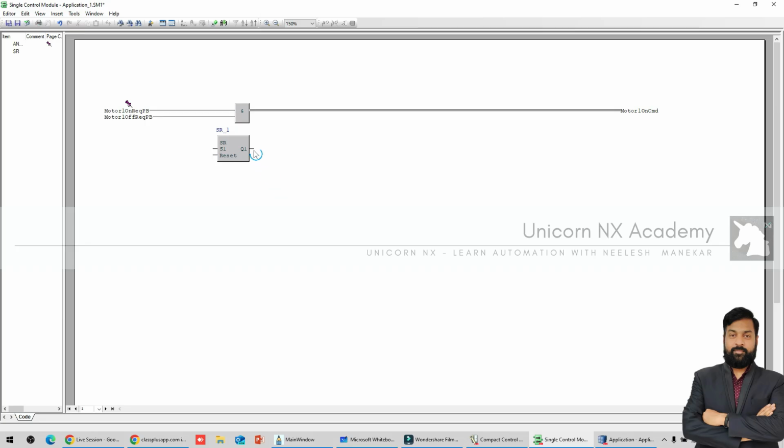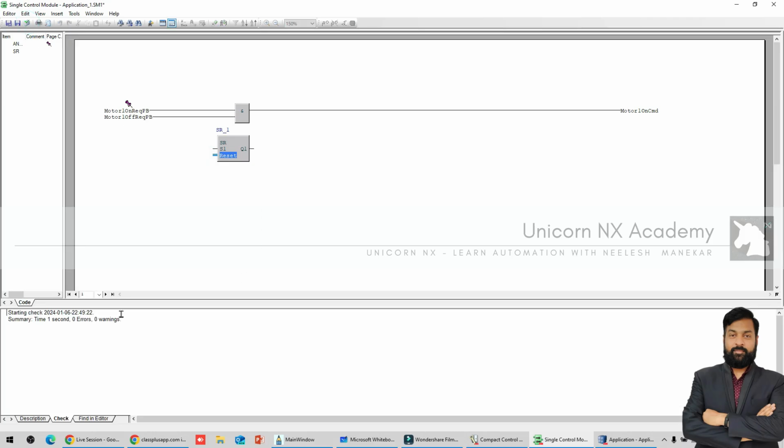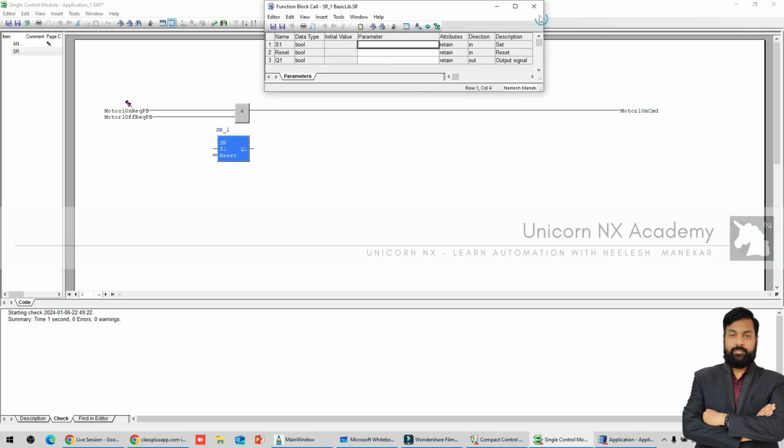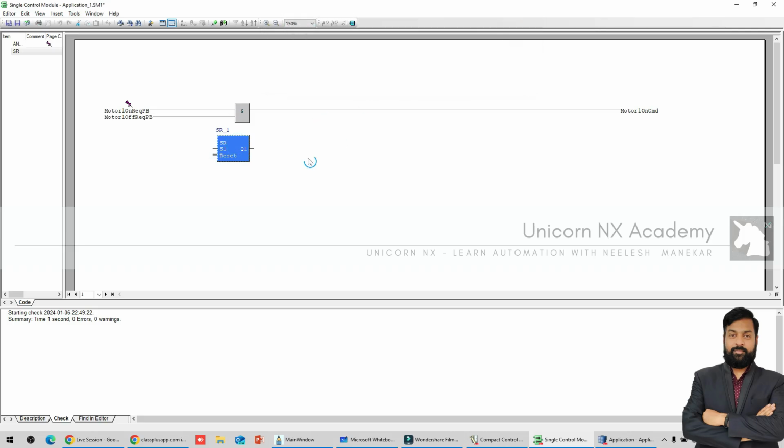Few function blocks support unconnected pins. So even if you check it now, it says okay, because it doesn't need connected pins, but a few don't support unconnected pins, so they will throw an error. In general, system function blocks must have a connected pin there. But if it is a defined function block, you can have unconnected pins also.